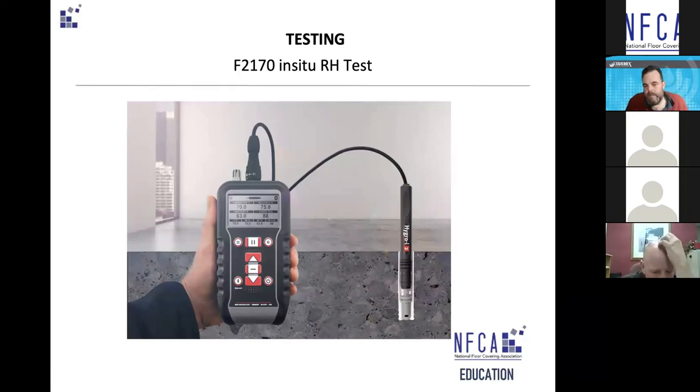So the 40% depth becomes important when you're measuring vapor, because the theory behind it, and possibly the fact behind it, I'm not certain, is that if you measure the vapor at this 40% thickness of the concrete, once you cover that floor up, that vapor will be what is at the surface. And that's where it gets really interesting, because if you imagine 85% RH being at the surface, that's your 10 degrees from dew point. And that's the bit that people probably won't get on this meeting.